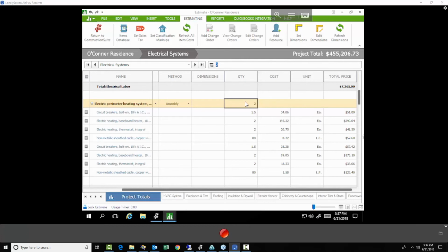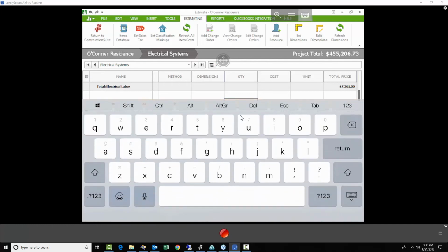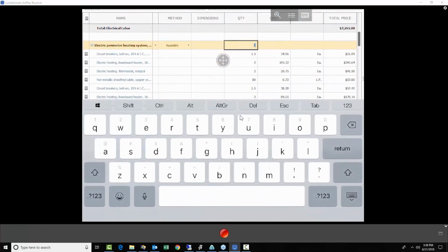If you have multiple units and originally you're going to be going in there to do some remodeling projects on, let's say, 4 units, and the owner of the building says, 4 is not enough, let's make it 7. This would allow you guys to go into and update these values extremely quickly, because now with this assembly method, updating or changing the quantity for the assembly itself, let's say we want to go back from a 2 to a 1 again, it's actually going to update all of the quantities for the individual parts in the assembly to fit this new quantity.